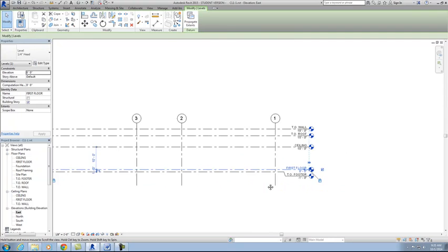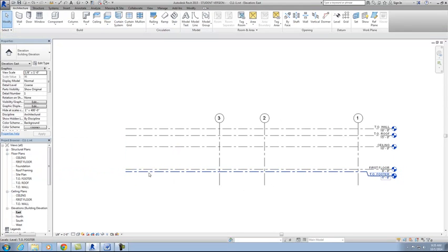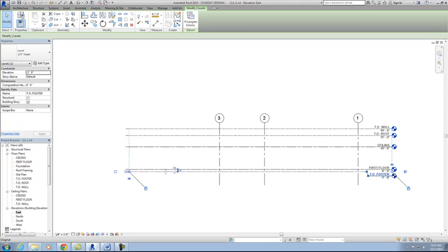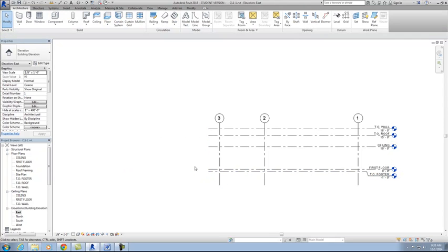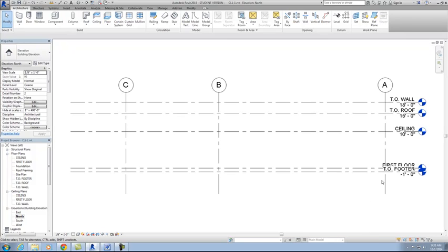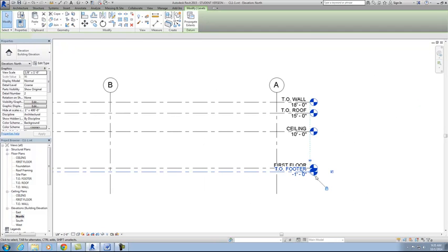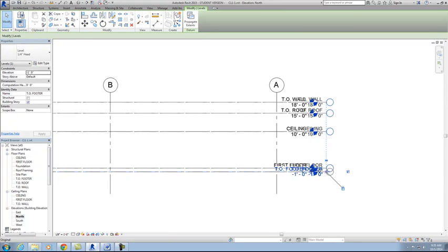So now we're going to drag over the other end of the levels. Now this is also going to move levels in other views, so just be aware that if you pull these in too close, it may move the other levels in the wrong way. So now let's go to north. Kind of see that result right now. So I'll drag these back out a little bit.